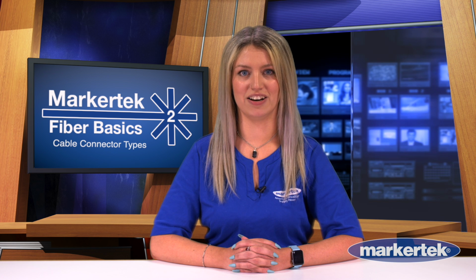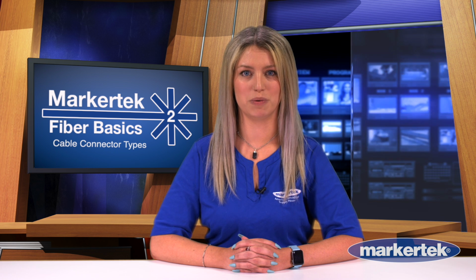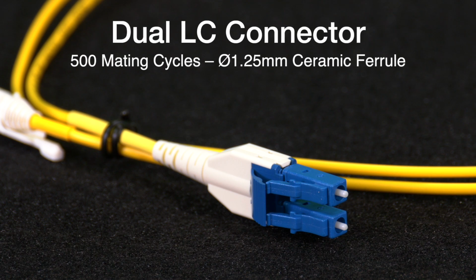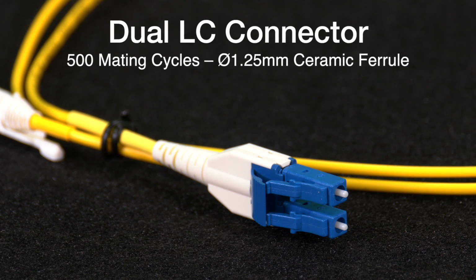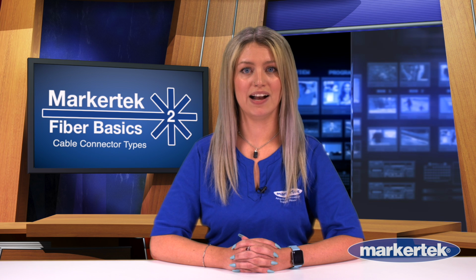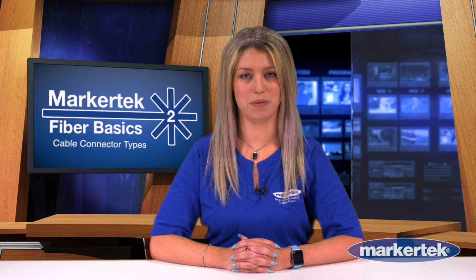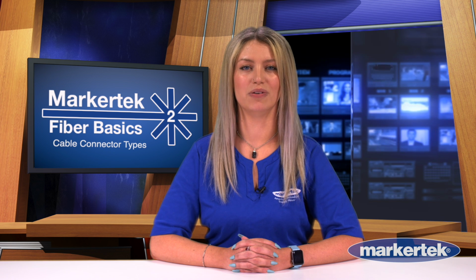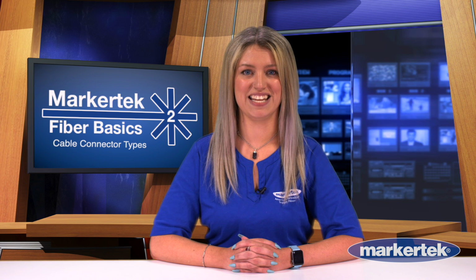The LC connector is very popular in high-density patch applications like Ethernet switches, as well as its use with video and audio extenders. It is very common to see the LC connector in what is known as duplex, which is just two LCs bound together in the same cable. LC connectors are commonly beige for OM1 or OM2 multimode, aqua for OM3 and OM4 multimode, or blue for single mode.